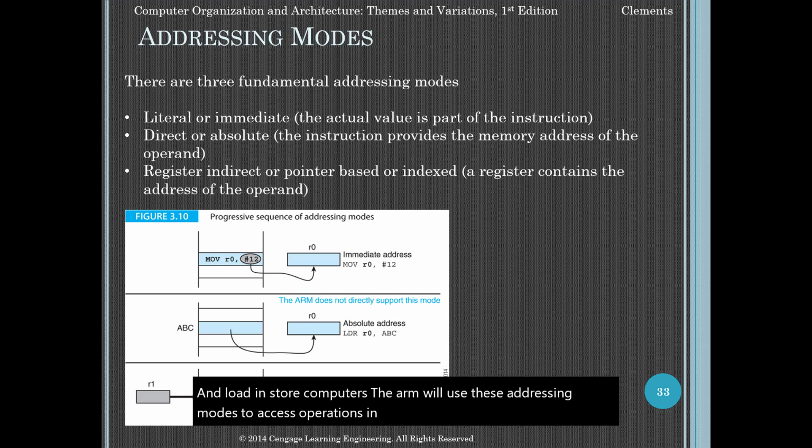And so when you write your ARM code, and you'll see this where we do the LDR and we specify register 1, and then we point to register 2 to indicate that the contents of the memory location whose address is in register 2 should be moved to register 1. And in ARM, in Intel, in Freescale, all assemblers can write this. This is one of the most widely used ways to address.